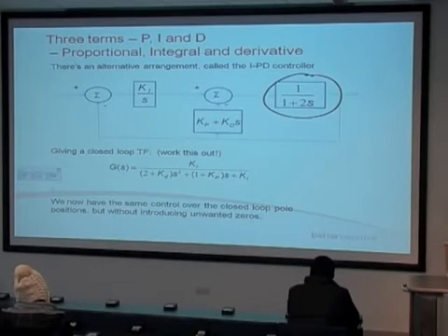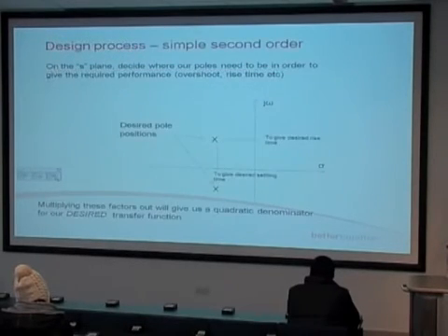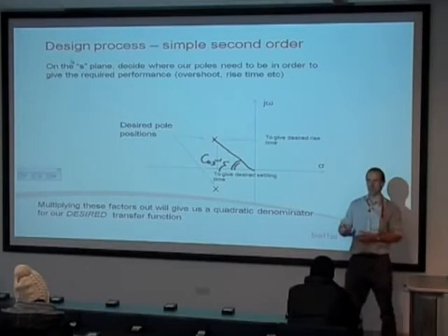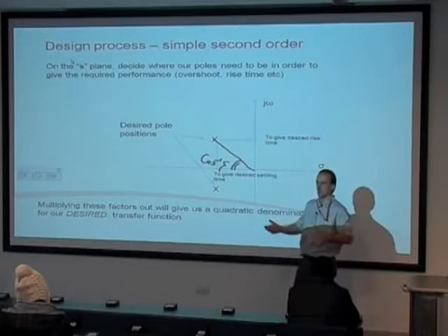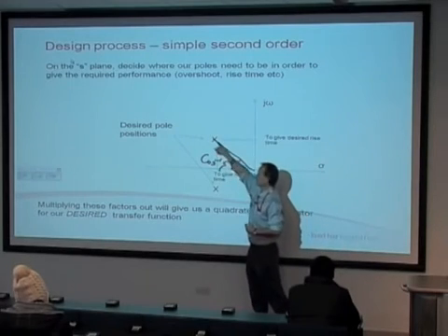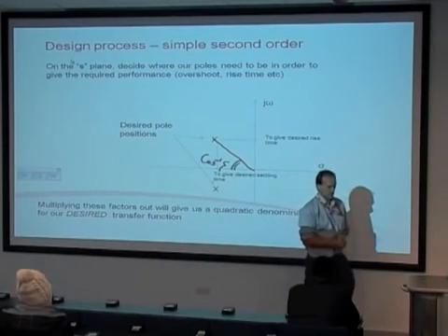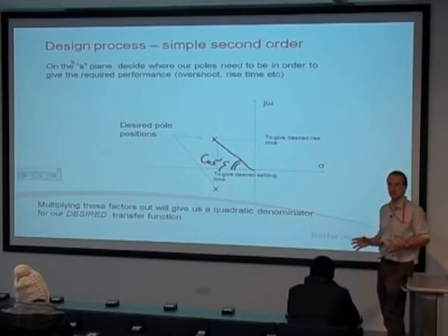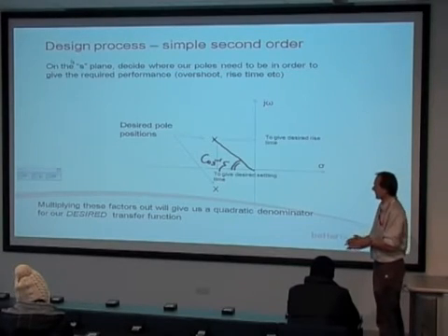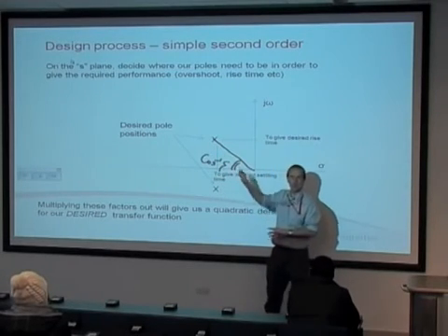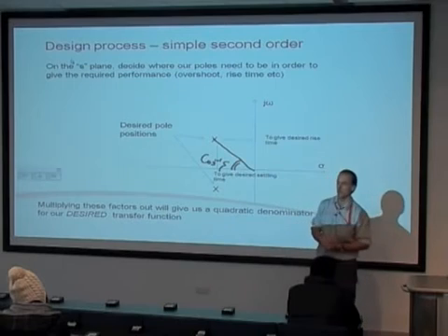So you think, okay, that's fine, I'll go on with my design process. But you don't just end up with two poles, do you? If I've got a fourth order denominator, or even a third or a fourth or a fifth or a higher order denominator, I'm not going to be able to describe it just with two poles. Which is a bit of a shame, really, because I quite understand second order behavior by now. I've got to terms with it over the last few weeks, and it would be really nice to design my desired transfer function using this straightforward second order sort of method.